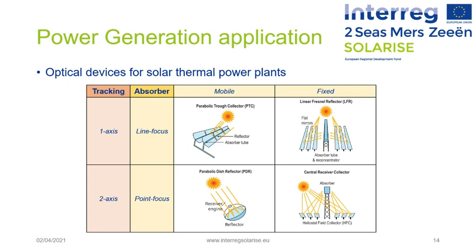In concentrating collectors, solar energy is optically concentrated before being transferred into heat. Concentration can be obtained by reflection or refraction of solar radiation by the use of mirrors or lenses. The reflected or refracted light is concentrated in a focal zone, thus increasing the energy flux in the receiving target.